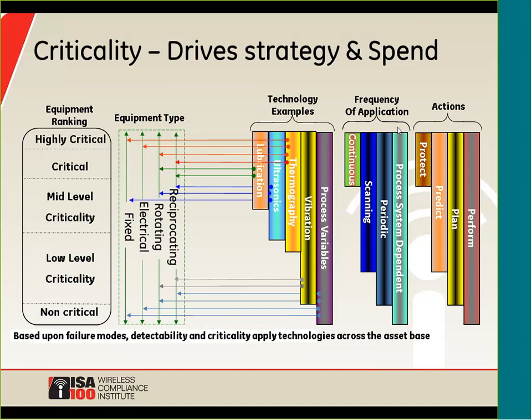For example, if you've got a pump going into cavitation, you can see that directly in the vibration levels, as well as in differences in the pressure differential across the input and the output. And again, depending on the criticality and the process that the equipment is involved with, that will drive how often you need to capture data from that particular piece of equipment.